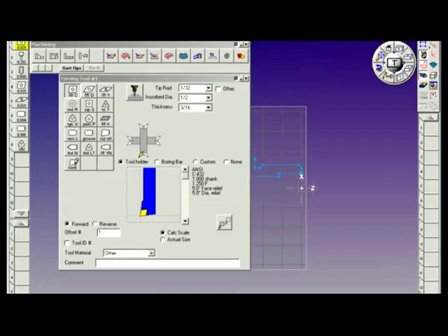A trigon, pentagon, a 55 degree style, top-notch Kennametal style roughing insert, rectangular, grooving, and cutoff inserts. Threading inserts, standard top-notch Kennametal style insert, cresting, laydown style, and a 35 degree threading insert with a radius.